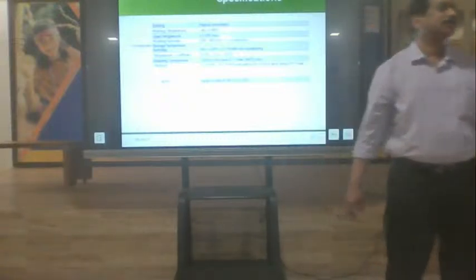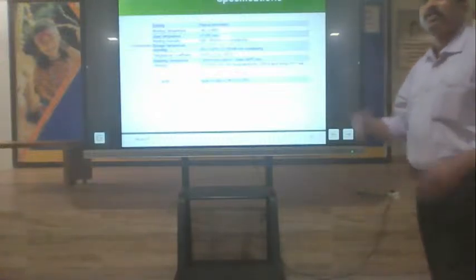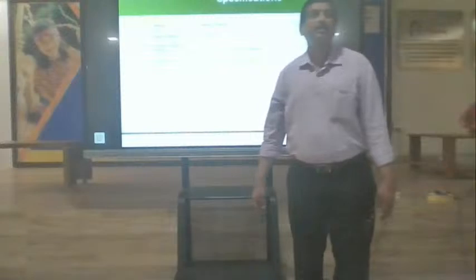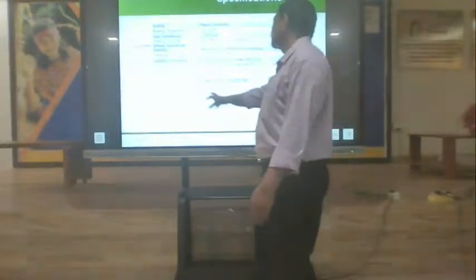Each device is like a human being: we are born and then we die one day, and the time between is our life. Similarly, an electronic component also has the same thing. The moment we start using it, it doesn't have an infinite life. It will fail at some point of time. That is called the mean time between failures, the lifetime of the component. It is 560K hours, so 560,000 hours. How many days?